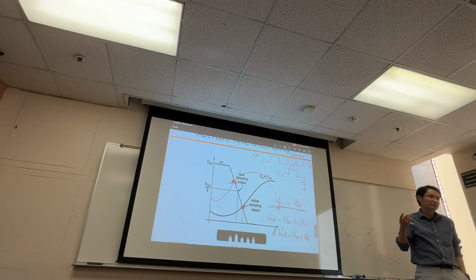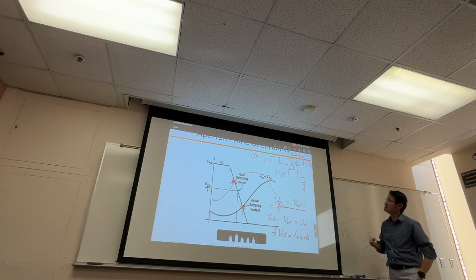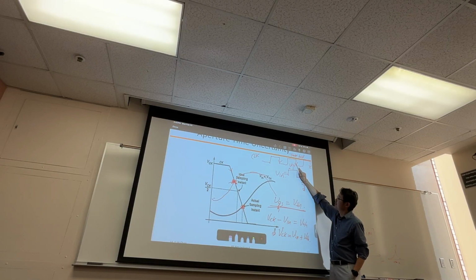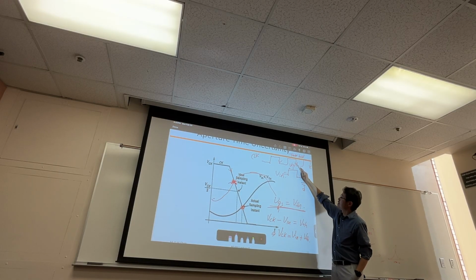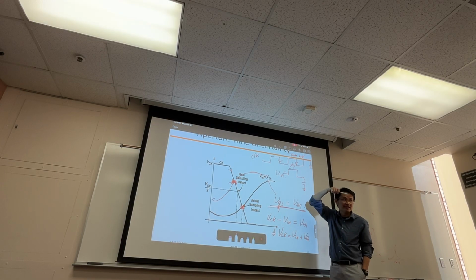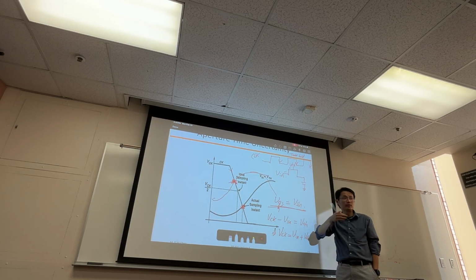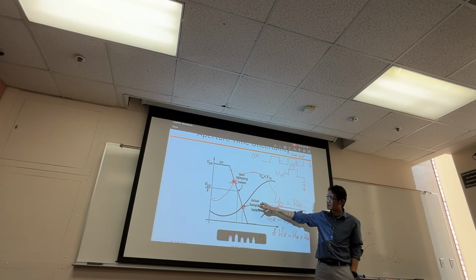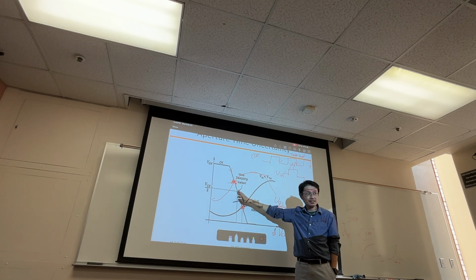You may be sampling at the point where you think, okay, it's just at the falling edge, and even if there's a finite fall time, you assume that's VDD over 2. That's usually how we assume. By the way, that's still a very reasonable assumption, so to the first order, that's what we assume. But if we zoom in, we realize that's actually not the case.